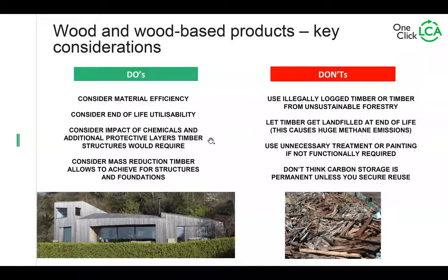So you have to consider all the layers you need to put in your building to make a fair assessment of it. And importantly, also timber is lighter. So mass timber is less light than a stick frame, right? But it's always lighter than equivalent concrete. And so do consider the mass reduction, right? So timber or steel for that matter, if it achieves a lighter building, is very desirable for locations where you would have very heavy foundations or you have earthquake risks, because if you can avoid having a lot of mass, then you don't have lateral shifts in case of earthquakes, and you don't have so much pressure in case of just tricky foundation conditions.